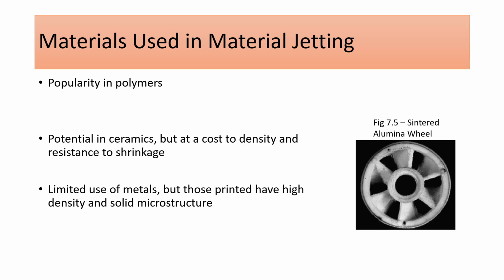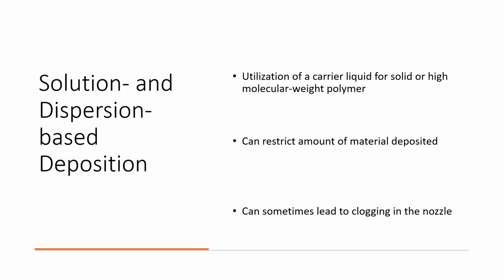Furthermore, the low concentrations of polymer and solid within the solutions and dispersions can restrict the amount of material that can be deposited. Also, it can be challenging to control the deposition pattern within the impact of the droplet, though this setback can be handled through control of the droplet drying conditions. Lastly, the main issue with this technique is that the use of more volatile solvents can result in premature formation of precipitation within the nozzle and cause clogging.